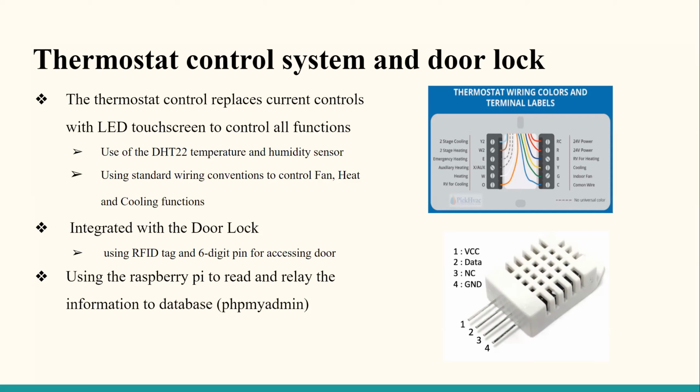It's integrated with the door lock, which is using an RFID scanner and RFID tags and a 6-digit display to access the door. And it's using a Raspberry Pi to read and relay information between the database using PHPMyAdmin. And on the right, you see a common thermostat wiring label that I used to connect it with my thermostat and is common in most cases in the United States. Then we have the DHT22 humidity and temperature sensor right there.